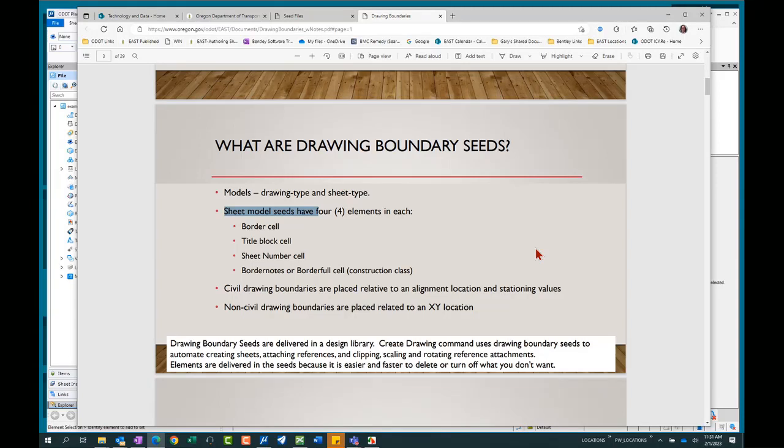Well, it's a model. It's an area to do drawings, but it has different properties than a design type model. In the past, we've used a lot of design type models, and we were just kind of breaking into using sheet models about 3 years ago. We really weren't using sheet models a whole lot. But when we went to the Connect edition of the products, we created print styles that print preferentially from sheet models, and they do a really good job of applying our standards and producing our standard products when they are produced in sheet models.